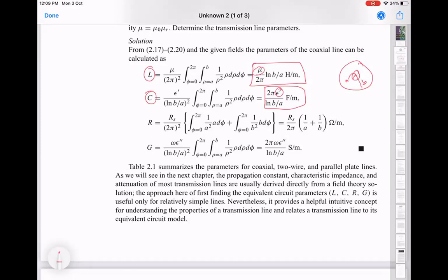So if you ignore the outside dimension for the moment, because that's sort of the ground part of it, the inductance will become larger if the center pin is thinner, and vice versa. Okay. Now, let's come back to the other one we started with. This part is a little bit subtle, but it is related to mutual inductances. It's actually the connection between the two conductors. Why? By increasing B, the inductance goes up.